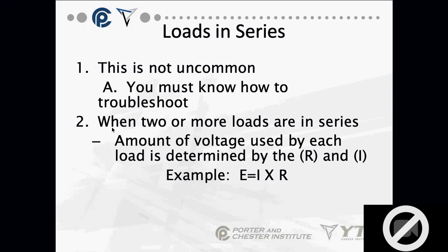Loads in series. This slide says it is uncommon in our industry. We do not see loads in series that often. I see it most often in electric heat. I don't see it that often in cooling. Loads in series split voltage, but you have to know how to troubleshoot.